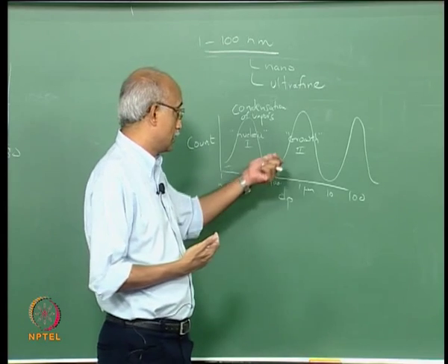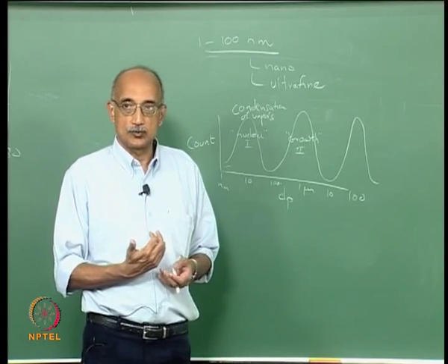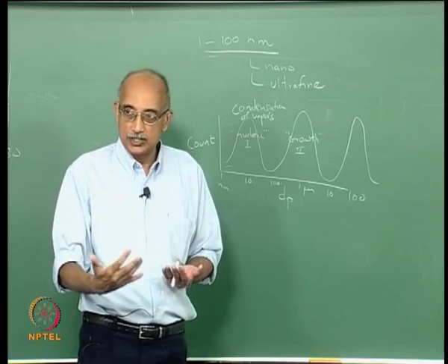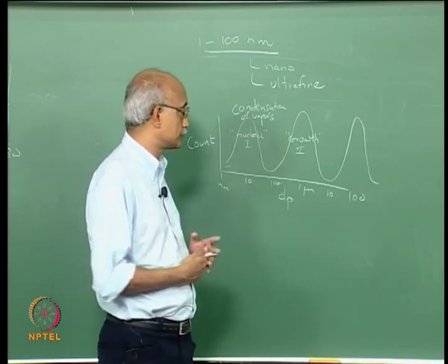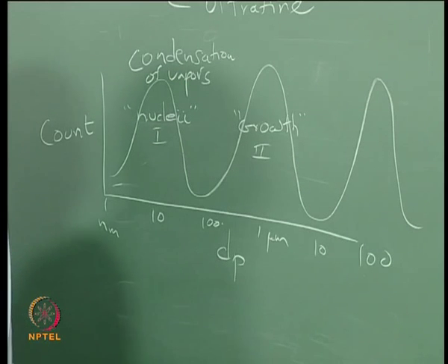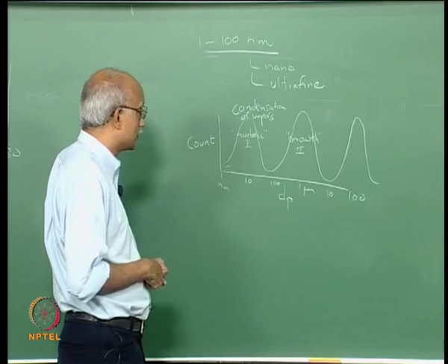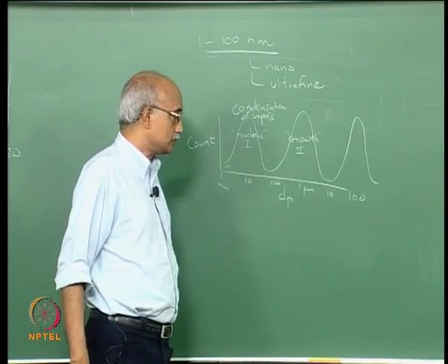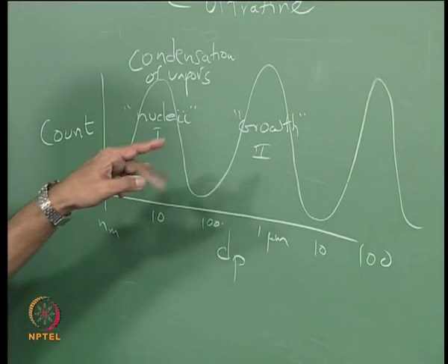And so the nuclei that we are talking about here can either form in a homogeneous mode or in a heterogeneous mode, and heterogeneous mode always has a lower energy barrier, and so it is much more feasible compared to homogeneous nucleation. The growth phase is essentially the phase where the initially formed nuclei find their nearest neighbor and start agglomerating.